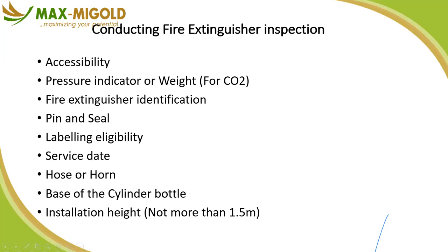So where you have an electrical panel, I won't expect to go and place a water extinguisher around that place. Within the building, it would then be a CO2. Outside the building, so maybe close to the transformer, it would then be a DCP, a dry chemical powder kind of extinguisher. All right. So we expect that, okay, that has been done.